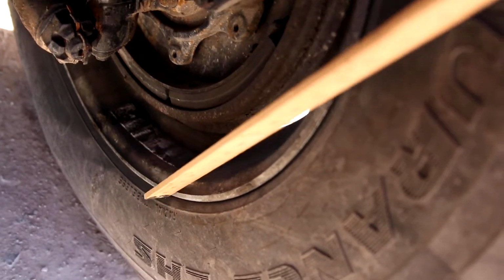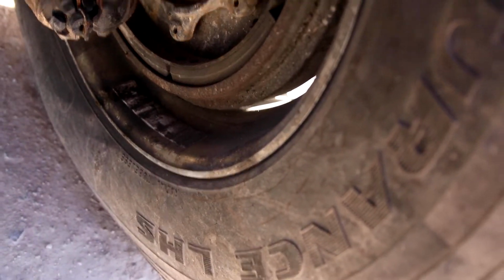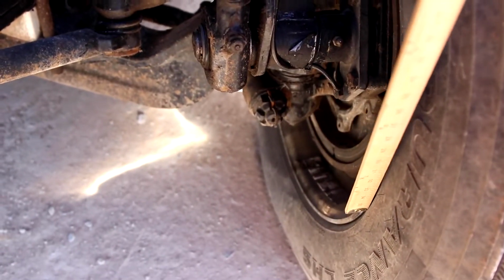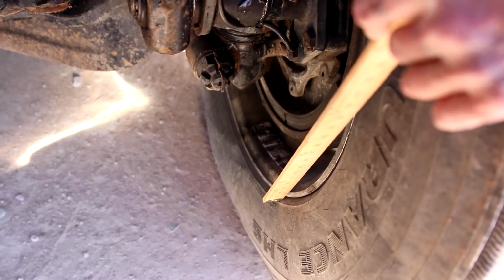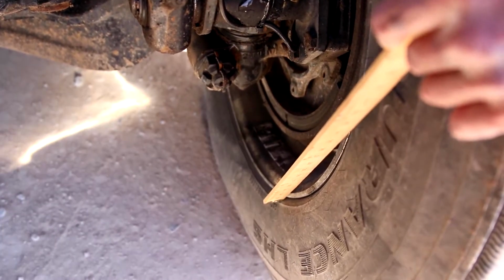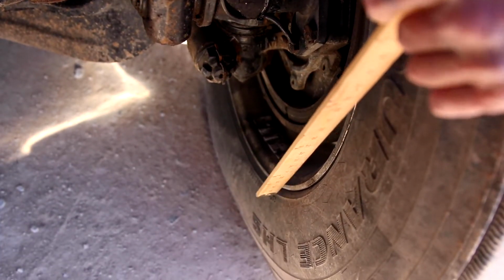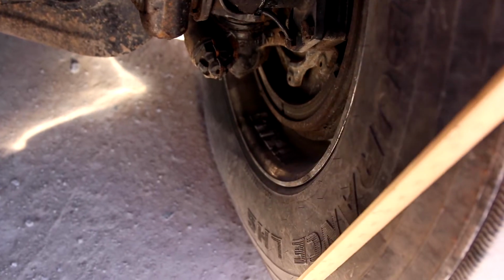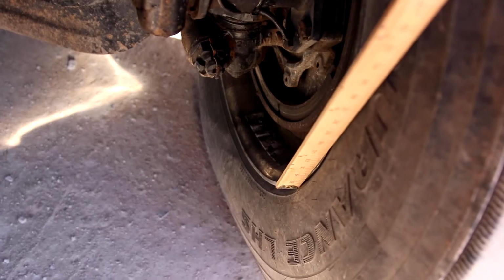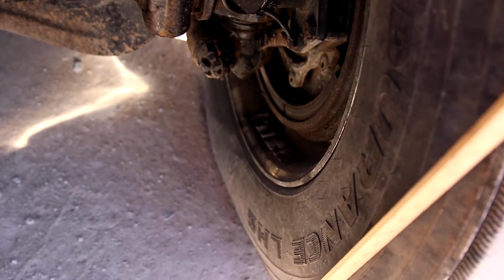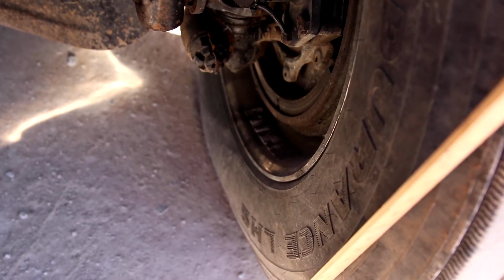This is your inner rim and outer rim. If you want to talk about that, my rim on the inner side is not missing, damaged, or broken. No illegal welds. The tire is mounted securely to the bead of the rim. It is not cut, damaged, or frayed for a blowout.